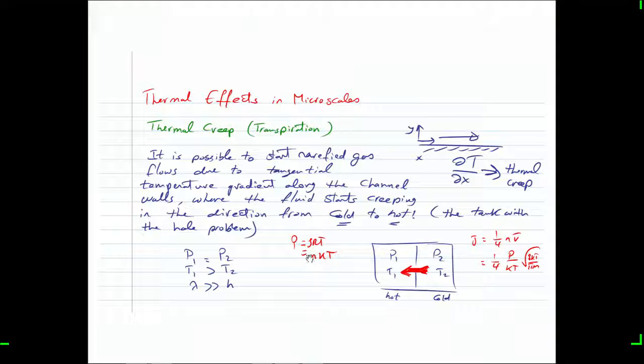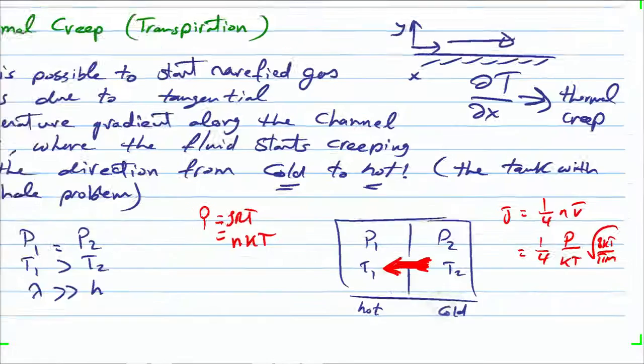So just like P is rho RT, there is also P equals N k T. The k is the Boltzmann constant, and it's not the temperature in Kelvin. The T is still the temperature, and N is the number density. So just like rho is kilogram per meter cubed, N is molecules per meter cubed. As I said before, obviously rho is m N, where m is the mass of each molecule. Very good.